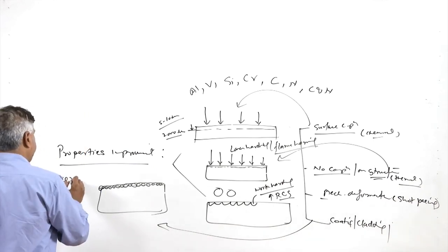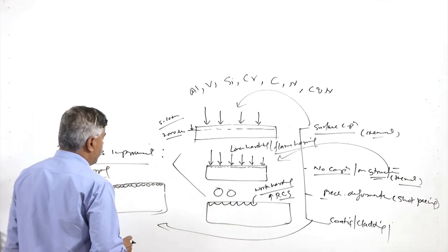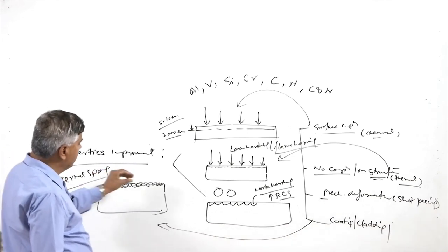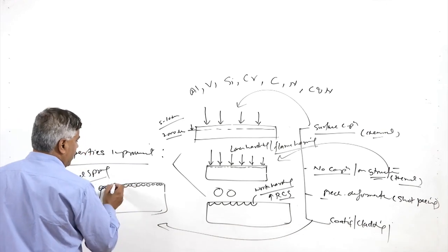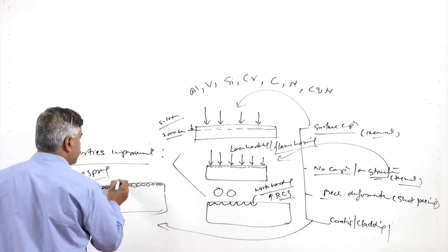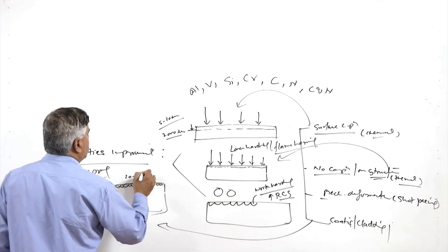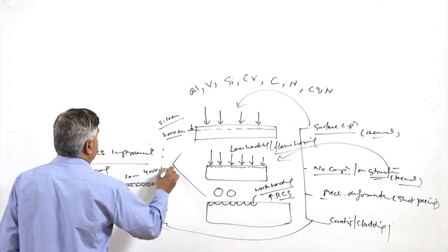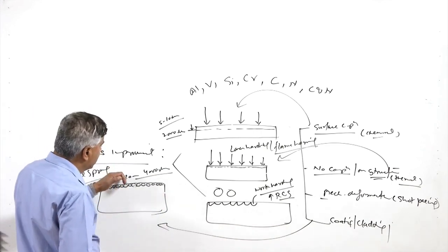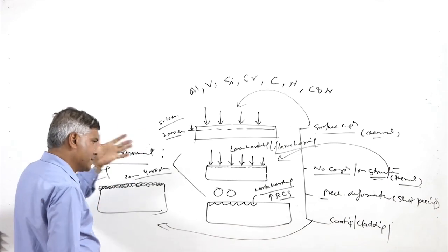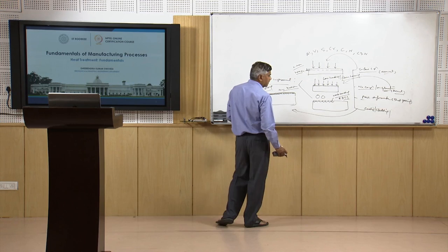Like thermal spraying, which is one of the categories of processes where a thin layer of coating is deposited, depending upon the kind of the metal systems. The coatings may be like 20 to 2000 or 4000 micrometers in thickness. So, the harder the metal, the lower the thickness, and the softer the metal, the greater the thickness of the coating normally deposited through thermal spray coatings.